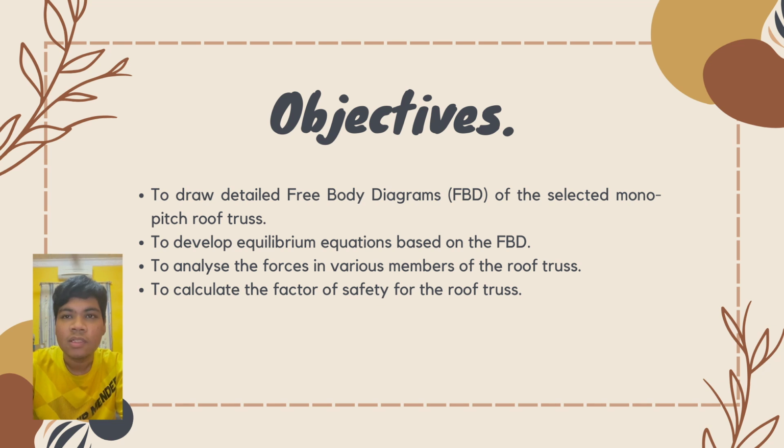So the objectives for this assignment are to draw detailed free body diagrams of the selected monopitch roof truss, to develop equilibrium equations based on the FBD, to analyze the forces in various members of the roof truss, and to calculate the factor of safety for the roof truss.